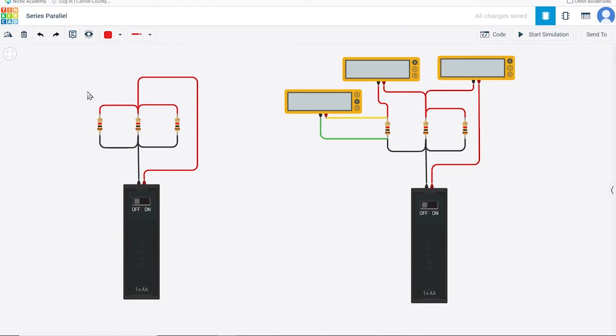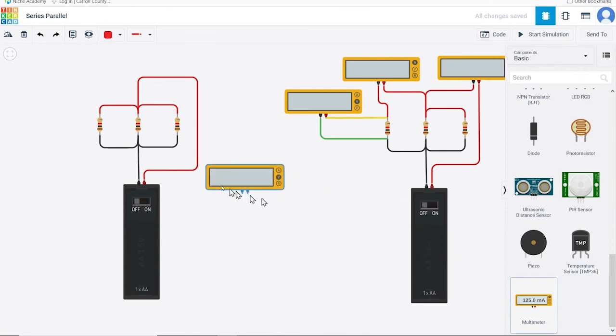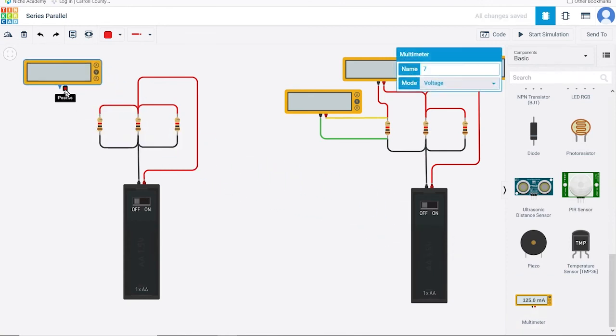Parallel circuits are exemplified by components that are connected side by side with respect to a start and end point. The example series circuit is rearranged by connecting each of the 3 resistors to positive and the other ends to the ground terminal. As before, we have an identical circuit to the right with multimeters connected to measure voltage and current. What is immediately evident is that the total current through the circuit is greater than the series circuit, 4.5 milliamps as opposed to 500 microamps.